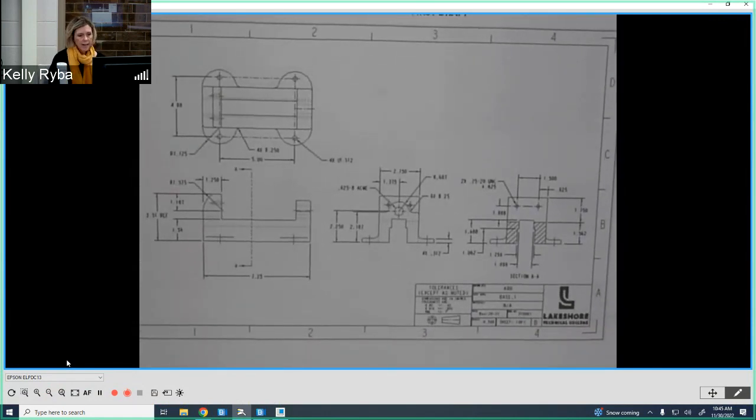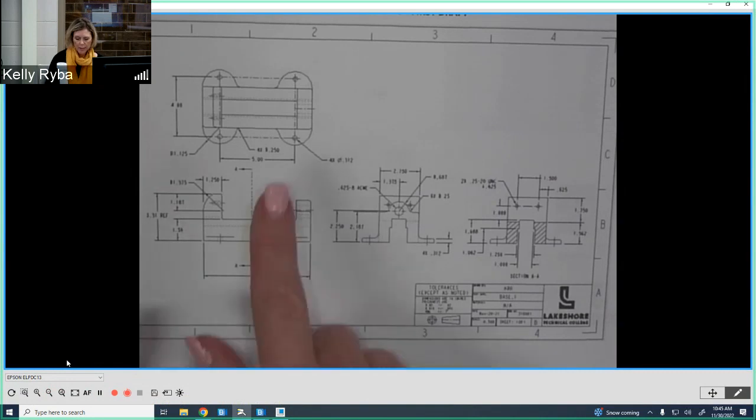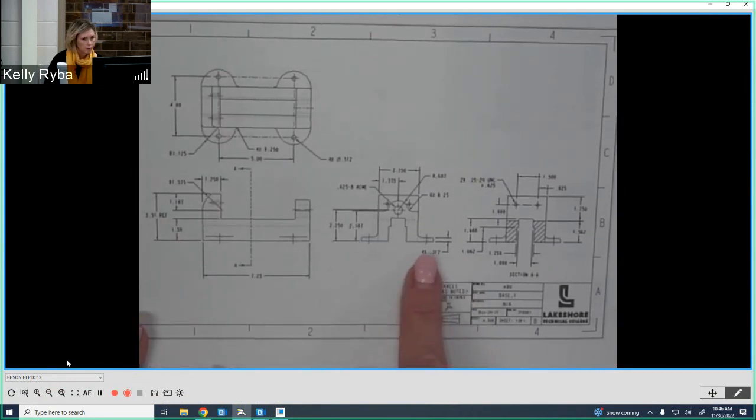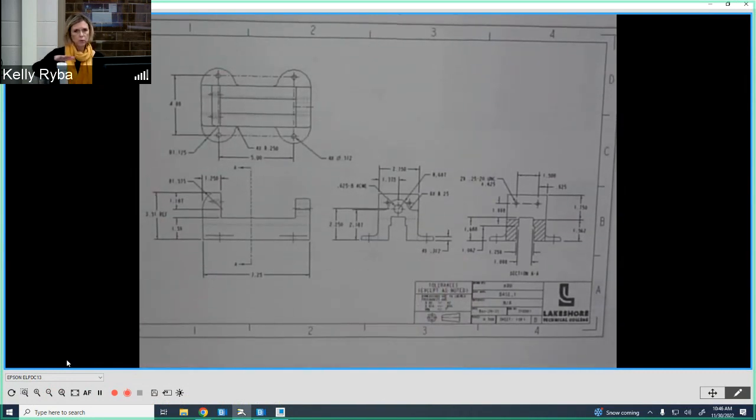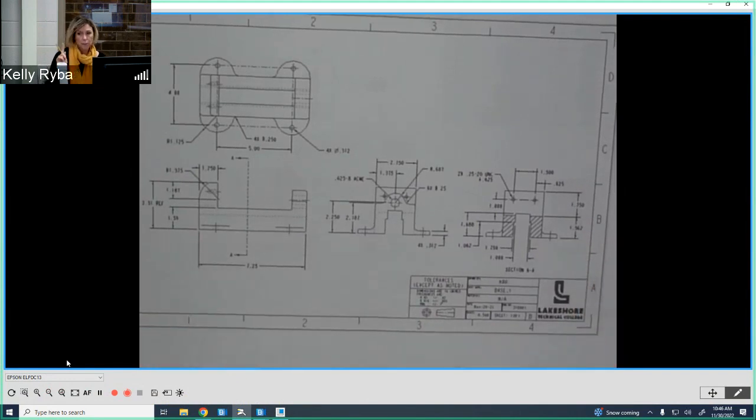So the things that I identified here that would be appropriate for this is, first and foremost, looking at the feet. So when this is sitting down, for instance, we want those feet to be on the same plane, okay? So we want this not only to be flat, if you would, but we want them to be on the same plane. So what that means to us is we need to then look at not flatness, because remember, flatness is going to be flat on one continuous surface.